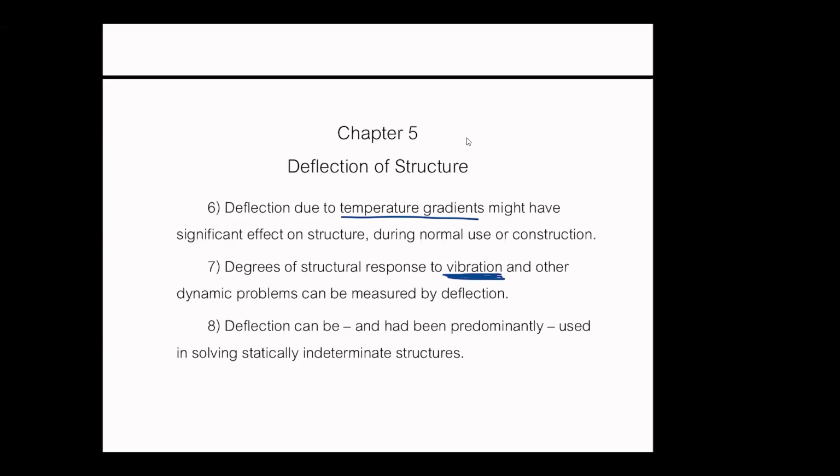So if you want a structure that can support the same amount of load, a concrete structure sometimes is not viable as it becomes too big. So they prefer the steel. But the steel structure, because it's not entirely solid, could have deflection. And especially somewhere like Broadway, where they dance a lot, human behavior can cause vibration, and we need to check that as well.